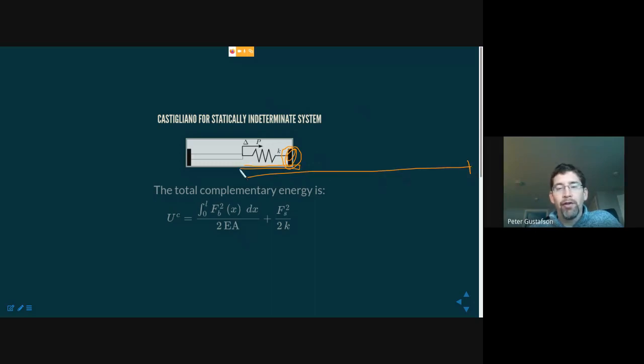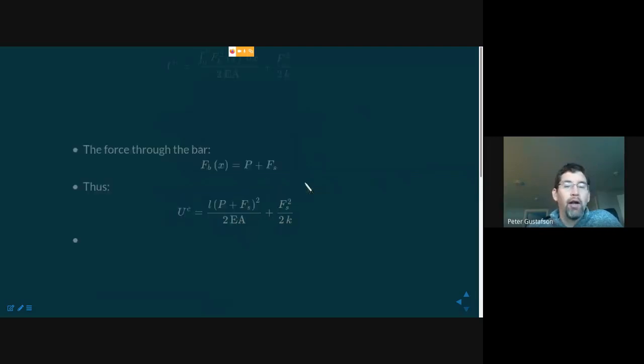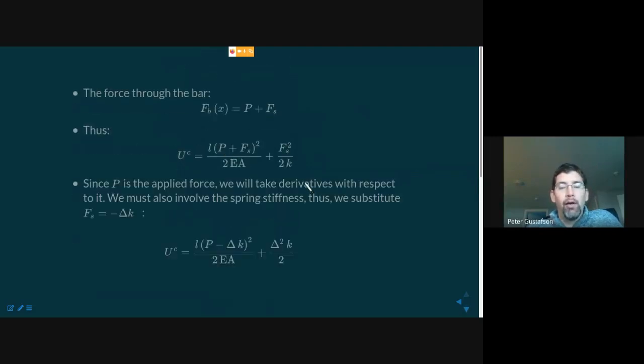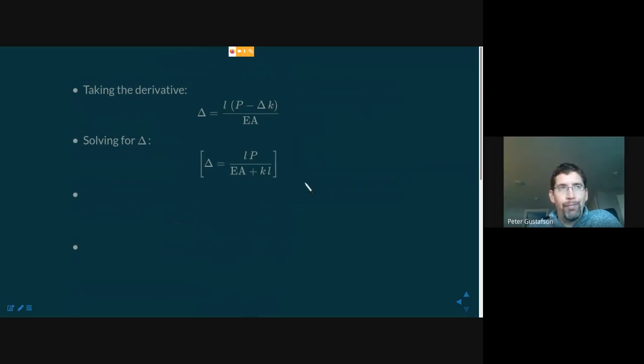Theoretically, you could stretch the original length to be 2 times the length. Where does that go bad? That becomes problematic if you get into nonlinear strength. For metal bars, you certainly couldn't stretch something 2x and still have it remain linear. So your point is well taken. But if it were a linear system, and you made the assumption of small strains, there's really nothing physically wrong with it going a full L, but I don't think that really has practical meaning. It's more of a theoretical discussion.